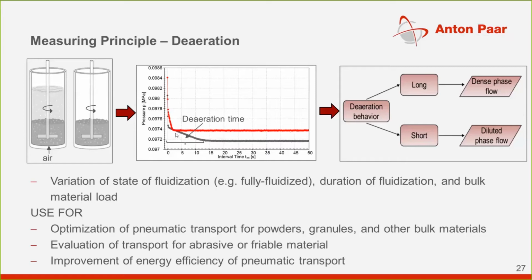And so this point where it stops decreasing, where the pressure becomes constant, shows us where the powder is deaerated. So in this case, if we look at the red sample, it is deaerated after about 2 seconds, while the gray sample is deaerated after about 13 seconds.